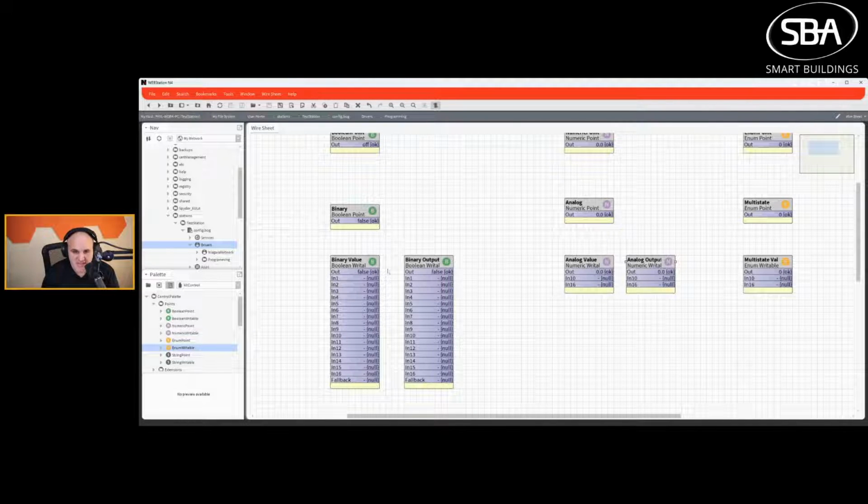Values should be set points. These should be logical software points. So in the case of binary values, this may be economizer enabled. So if the unit has an economizer, you command that BV on and it tells the unit to run like it has an economizer.